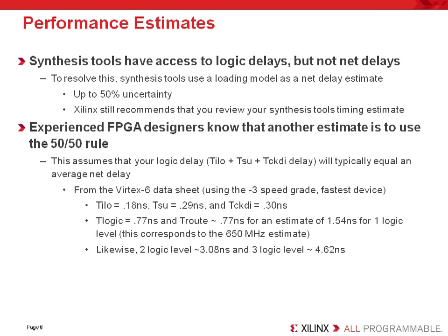Now, after you have built your design, you can get a timing estimate in a couple of ways. You can calculate a manual estimate from your data sheet, which is pretty good, and I'm going to show you a little bit how to do that. You can synthesize a timing estimate, which is also very good, but will require you to code the design. But I'll note here, synthesis tools tend to use a loading model, and that tends to be a little more pessimistic about the routing delay, which is not bad, but you need to understand that there's a flaw in the estimate there. A lot of synthesis vendors would say, well, we all do that so we don't get sued or whatever. Well, that's okay. But the key thing is for you to understand that that number usually is a little pessimistic.